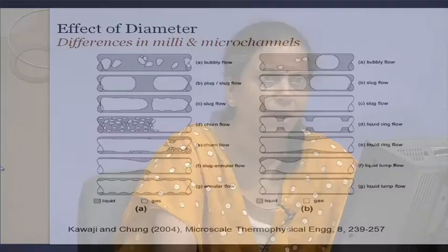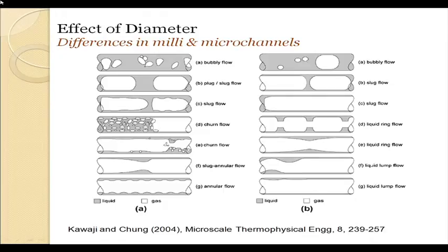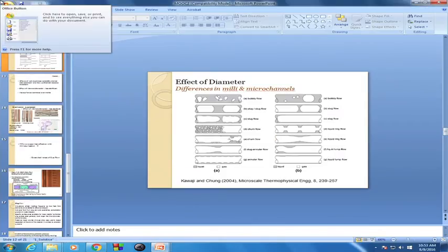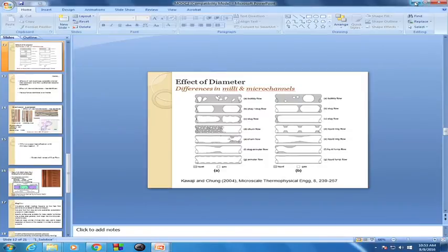So usually we find that churn flow is marked by three particular phenomena. The first one is a serpentine-like gas core, and this is surrounded by a deformed liquid film. Now, here I would like to tell you one thing. Such a serpentine-like core used to be observed when high viscous oil and water used to flow in a circular pipe. I will just show you a slide in order to highlight this particular situation.